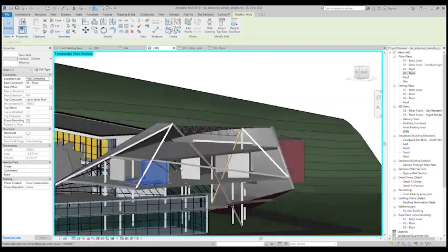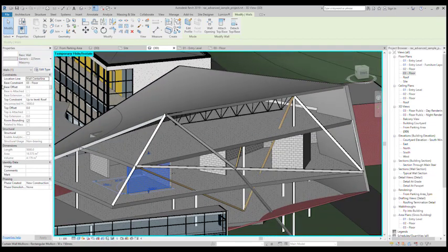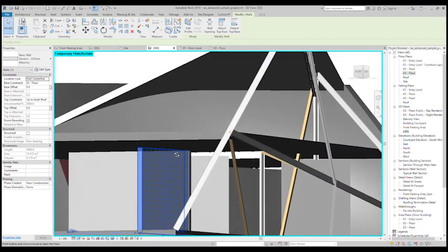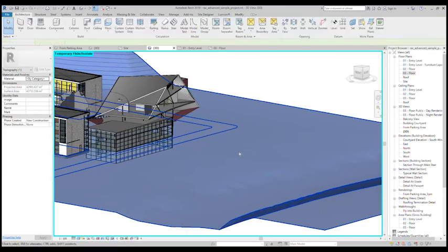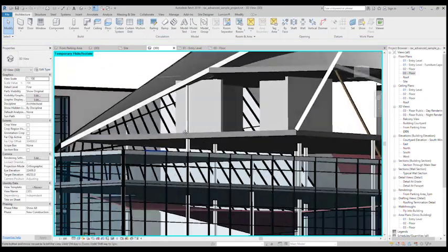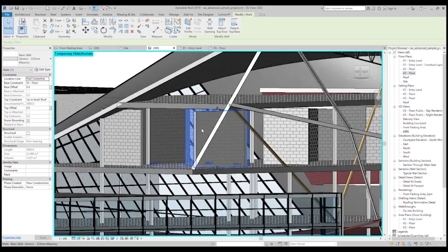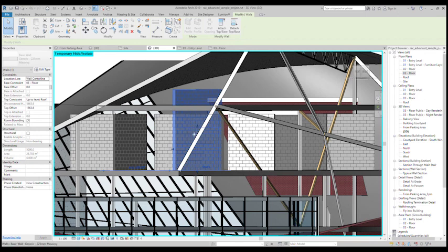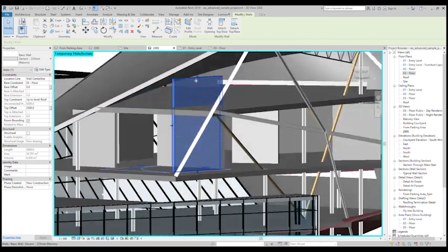Now, walls, as you've seen, if we click on a wall and we look at our property panels, there we can control its level and its height. So if it's relating to a specific level, which it is doing now, you guys can see that's where it's going to. I'm going to hide the topography. It's constantly getting in my way. Okay. Now we can offset it by dragging it with these little handles. Okay, change its height like that. You guys can see there the offset is changing. You can enter a numerical value directly like that if you know what it needs to be.